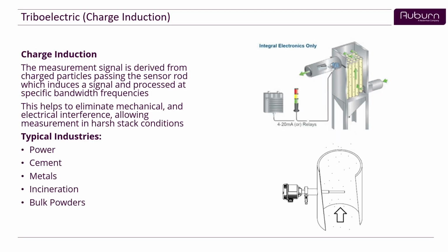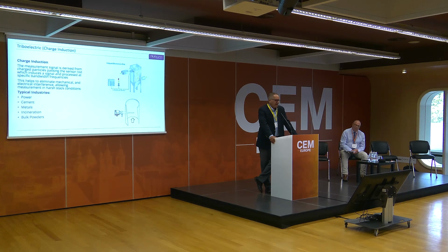Next, triboelectric or charge induction. A probe rod is inserted into the process, and as the particulate goes by the probe, it induces a charge. The electronics captures that charge in a specific bandwidth, and measures and reports the output in a human readable form.